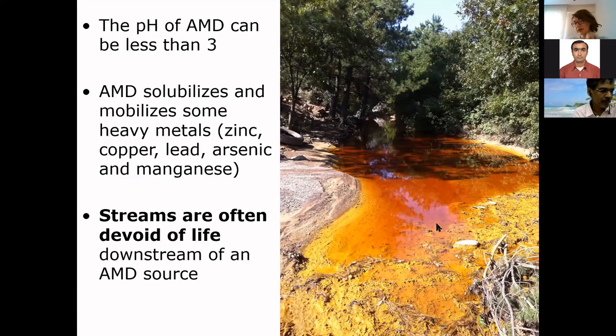Here, electrokinetic remediation for us, the problem is the electrodes, because our electrodes are having corrosion. Because of the corrosion, the electrodes are finishing. Yeah, that's a very good point. Corrosion is a major issue because pH is so low.